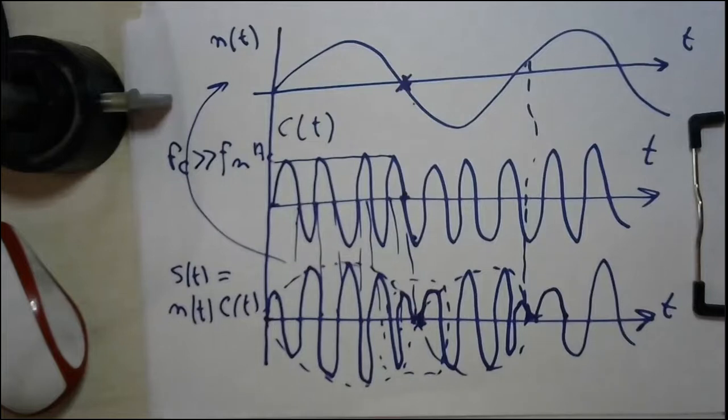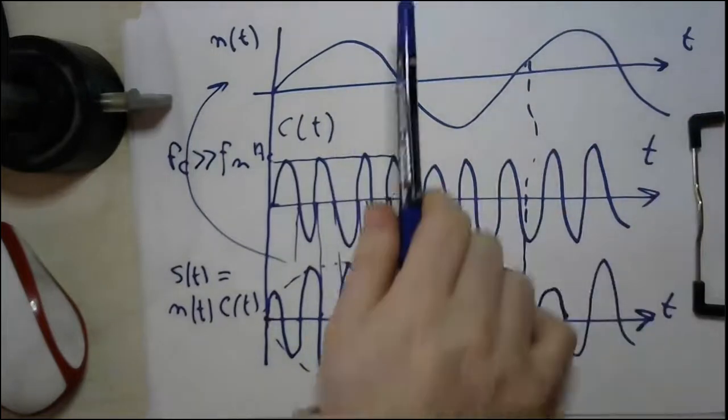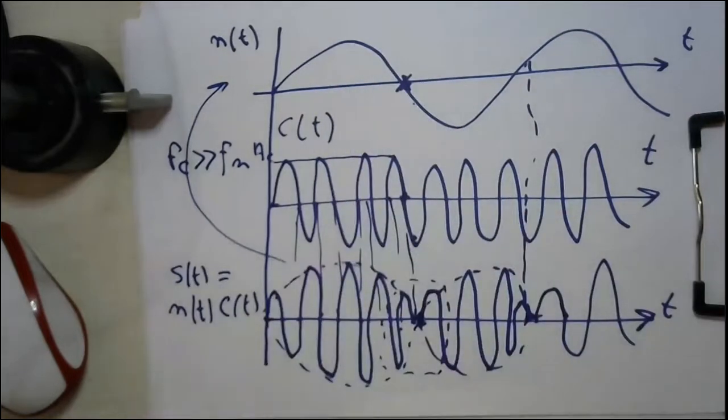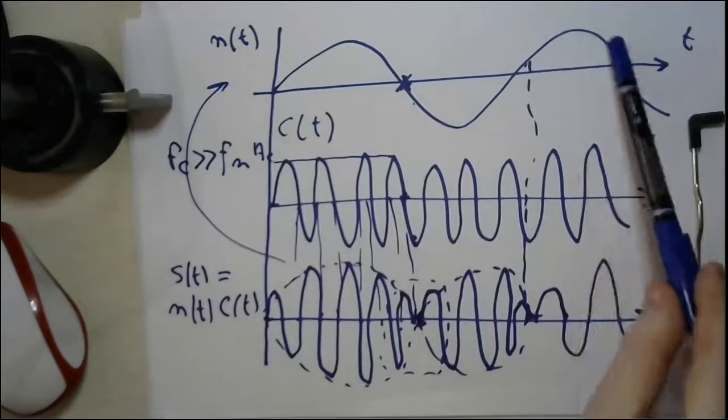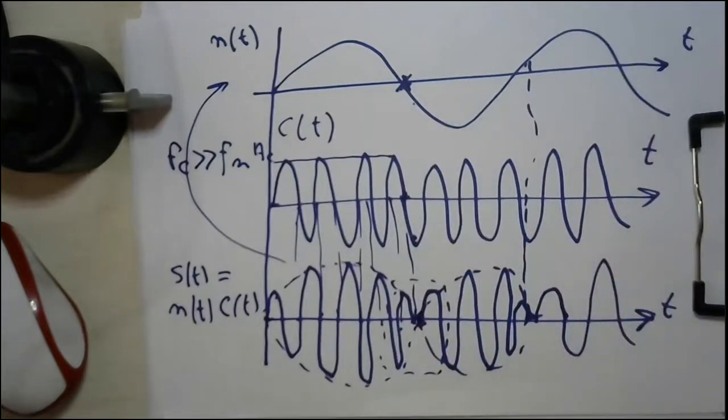If you remember the word DC offset, whenever we add a DC offset to a signal and shift it upward, all the message will be in the positive portion, mathematically in the first quadrant, and we will avoid such an alternating message in the plus and the minus region.